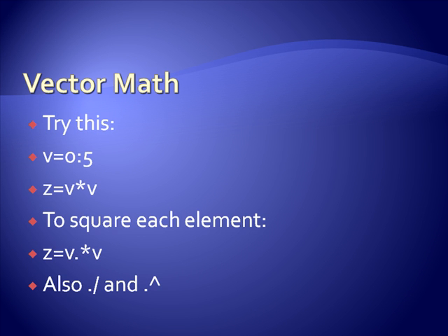Okay. In this class, we will basically never need vector math. So if you're at all unsure about whether to use a dot operator or not, just put it in and it's not going to hurt you. As you get a little more sophisticated with MATLAB, you can write some very efficient scripts by taking advantage of the vector math. But at the level we're going to deal with MATLAB in this class, you won't need it. Okay, so when in doubt, put in the dot with the operator.